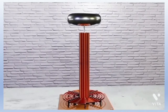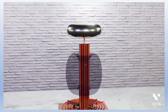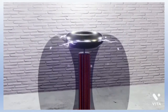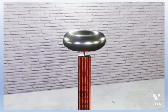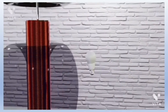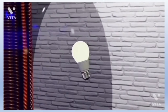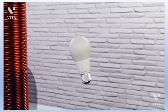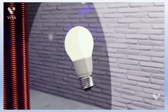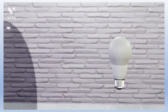The electrical discharges in the air are striking, but in reality do not fulfill any function. We could even say that they are undesirable, so we will keep our Tesla coil at a lower voltage to avoid these losses, and to only generate the electromagnetic field. If we position a fluorescent lamp near the coil, it will turn on, because the electromagnetic field will give it enough energy so that the gas inside starts emitting ultraviolet light, which is later transformed by a phosphor layer into visible light. The distance at which the lamp will light is quite short.